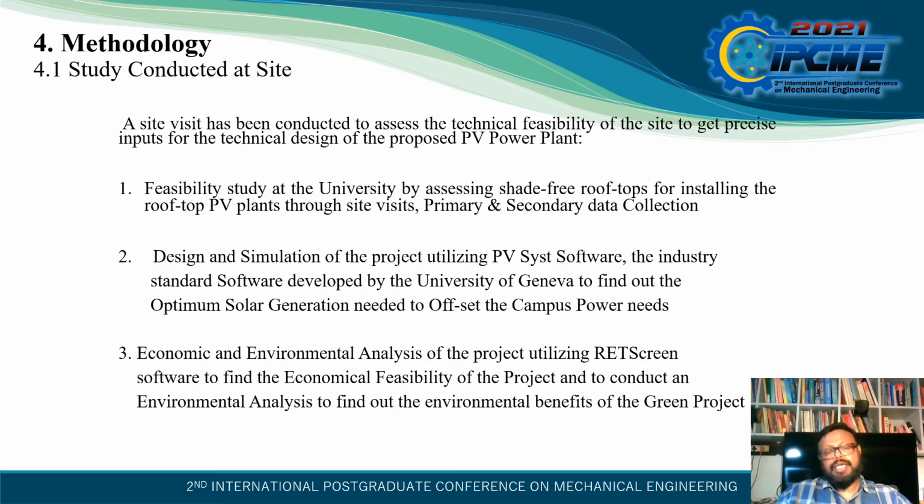The methodology includes a site visit and feasibility study, including primary and secondary data collection; design and simulation of the project utilizing PVsyst software, the famous software, to find the optimum solar generation needed to offset the campus power needs; and third, the economic and environmental analysis of the project utilizing RETscreen software to find the economic feasibility and the economic benefits of the project.